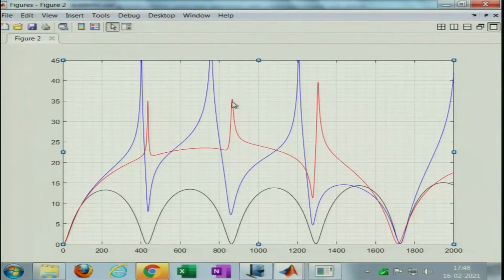So what happens is that for experimental results, there will be full contribution by the 3-dimensional modes. Okay, there will be evanescent waves that are generated at the interface, the port chamber interface, or at the interface where the perforated pipe starts and where the extension ends. So at the interface there will be higher order modes generated.